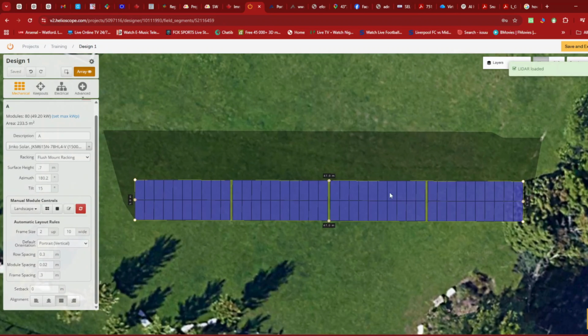Now this spacing, am I confident? Because most of the time, what I want the spacing to do is for people that are probably maintaining or installing to have space to pass. But they won't want to be passing, so they can still walk down, pass through and come. So after 2 frames they will pass to the other side. So what I can do, I can decide to increase this to 1 meter.